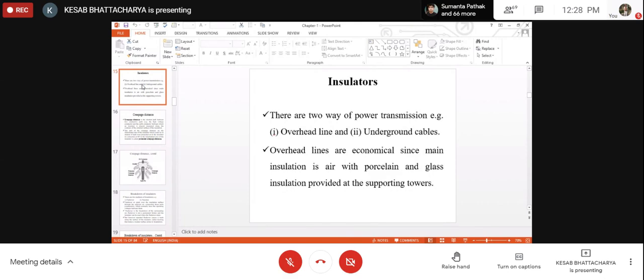Now you have two transmission lines, both are AC. Say one is operating at 50 hertz and the other is operating at 60 hertz. So you cannot directly interconnect them. What you can do is rectify the AC transmission at 50 hertz, connect it to the DC line, and on the other end of the DC line, you invert the DC to AC and connect it to the AC transmission line operating at 60 hertz.